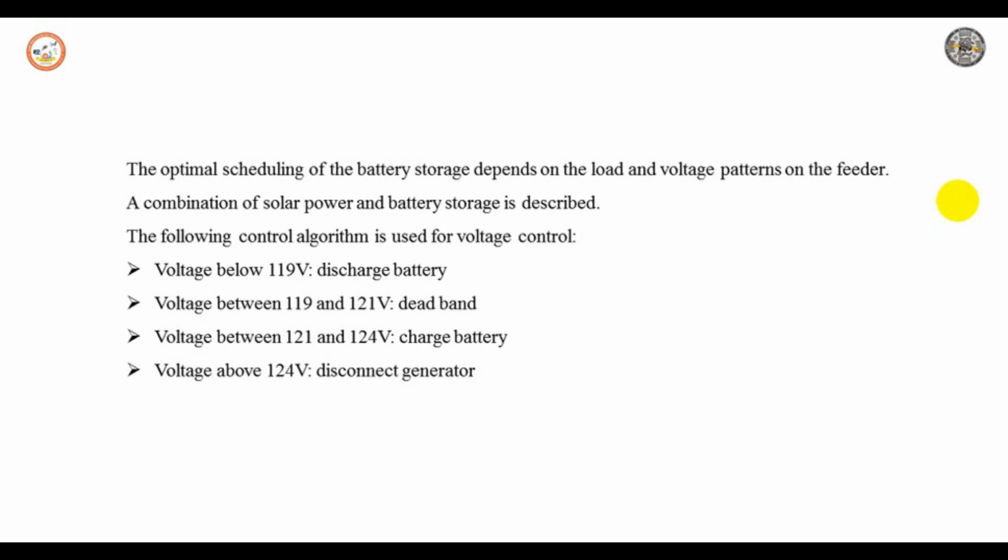Also, you can see that local battery storage in combination with solar power has been studied in Japan. In one experiment, a total 4 megawatt photovoltaic generation is combined with a 1.5 megawatt battery system for a 5 year test. The installation is connected to a 33 kV network. One of the aims of the study is to develop the control algorithm for optimal use of battery storage, where conflicting requirements are fulfilled, including participation in the electricity market and prevention of overload and over voltage.